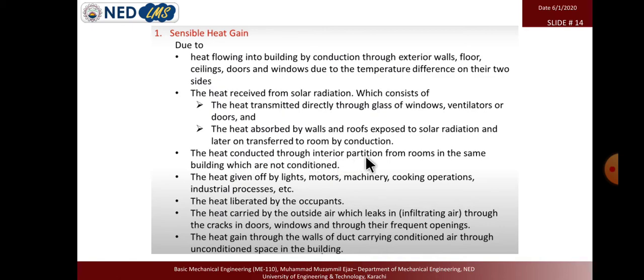The heat conducted through interior partitions from rooms in the same building which are not conditioned. The heat given off by lights, motors, machinery, cooking operations, industrial processes, etc. The heat liberated by the occupants themselves, and the heat carried by outside air. Yes, in Karachi the outside air has a very high, not sensible heat but latent heat. It has a very high amount of moisture in it.